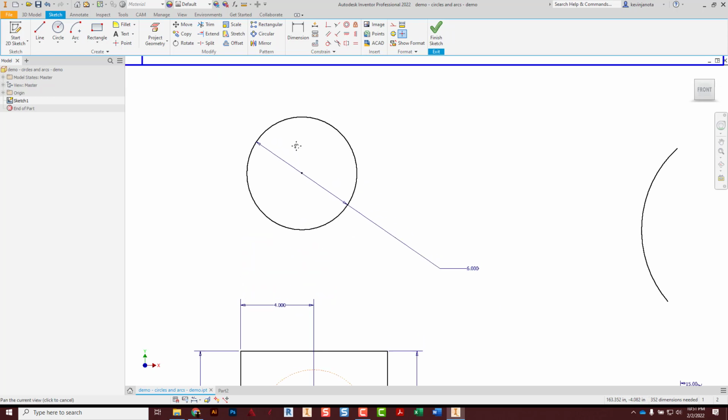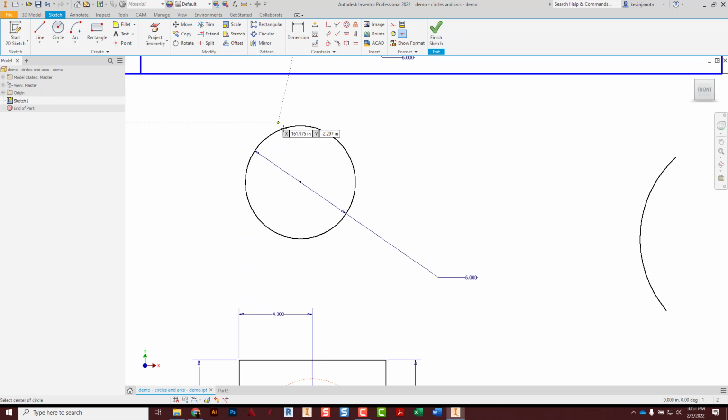Okay, so first one here, got a circle, and let's say we kind of are doing this. I'm going to put some smaller circles on there. Maybe I want like a little bump around all the way around and get that kind of shaped up the way I like it. I'm presuming I need it straight up at 0 degrees. If I need it at a different angle, I would put a line in and constrain all that like so. But then I go up there and get the circle pattern tool.